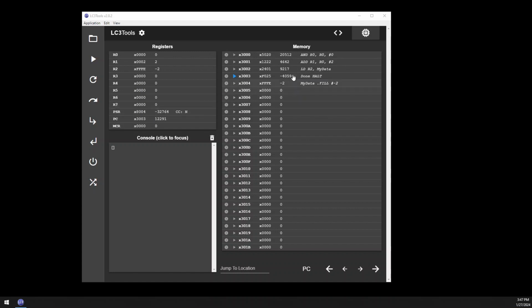A couple of other interesting things here on Simulate. You can see we've got a lot of buttons here. I was clicking on this one to execute each instruction one at a time. I can click here to run the entire program to completion. There are some other debugging tools such as step into and step out of, which we'll talk about when we discuss subroutines.